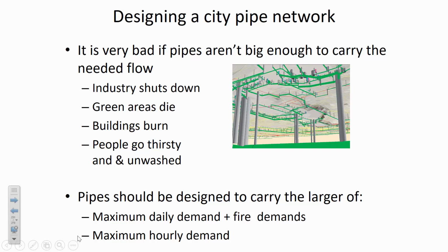And the same kind of idea is going to apply at the golf course. Maybe what you did was you looked at during the drought periods, like the driest year, the driest month in the last X number of years in your town. How much rainfall are they getting versus how much water does the grass need at the golf course. And so maybe you found that the difference between those two is you need to provide half an inch of water, and you multiplied it over the area, and you've turned it into a volume of water that has to be delivered.